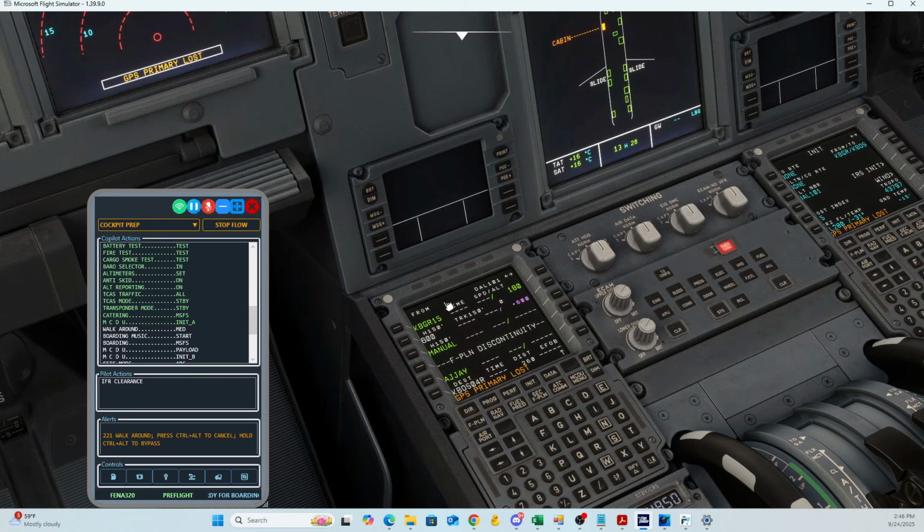All right, so after we selected our SID, STARs, and runway, we're going to clear our discontinuities. There we go. And again, these discontinuities after a manual, you cannot clear them. Those are there by design. The programmers thought that the pilots needed kind of an awareness that after this, ATC will give you a vector, which is why that cannot be cleared. So now our route is good to go.